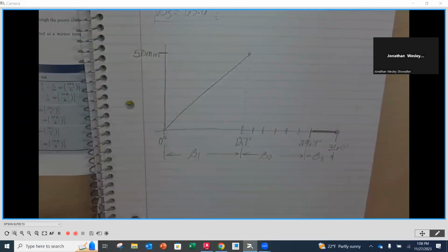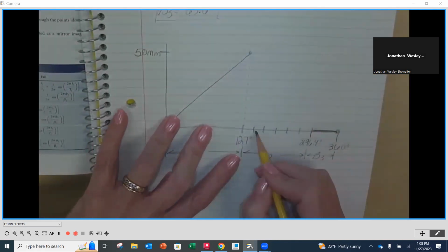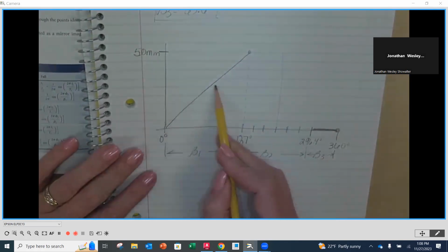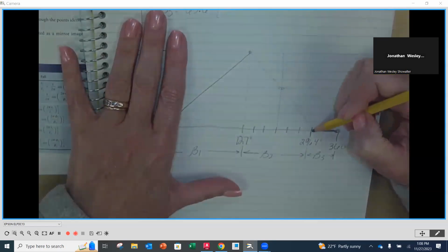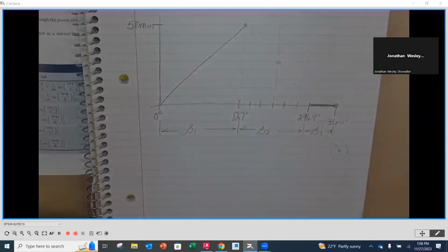This is a dwell. Okay, our total fall is going to be just in this section here. So what that means is, as we come down, this is our middle, right? This is our middle. And right about here is our middle. We're going to go through here, through here, through here, and we're going to construct our circle to have its center right down there. Does that make sense? I'm just kind of sketching the process right now. That's what I want you to get the idea of,